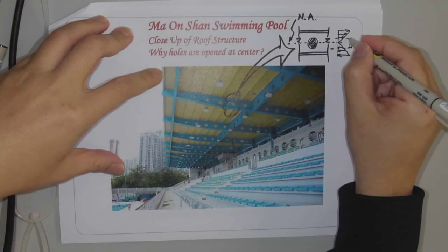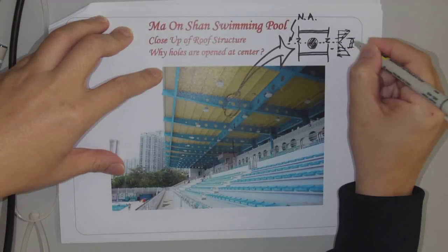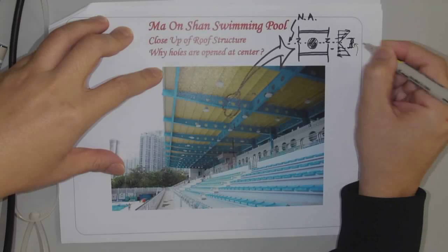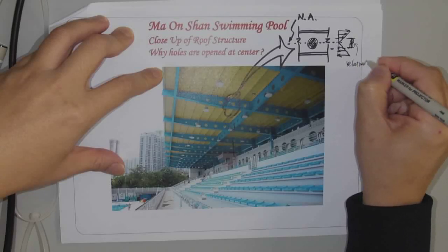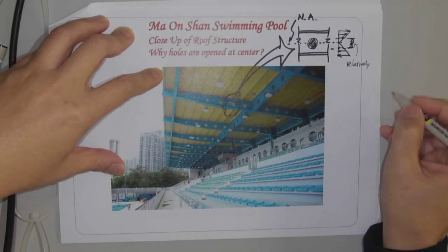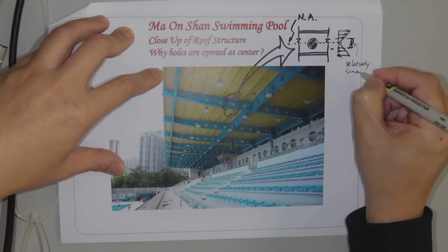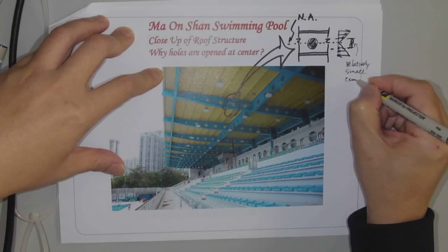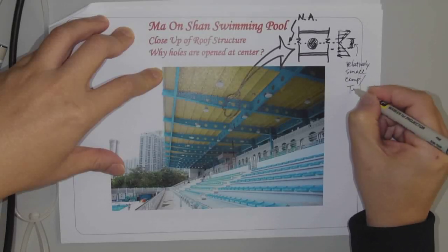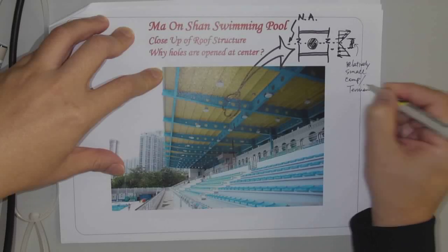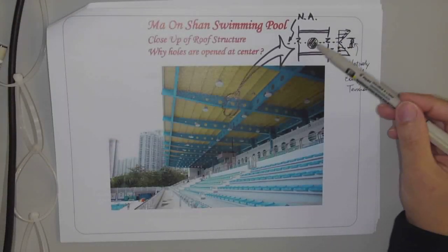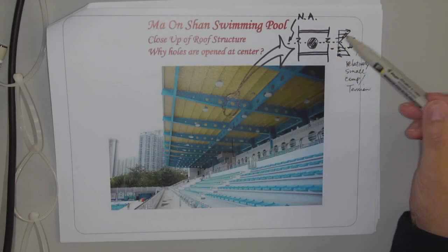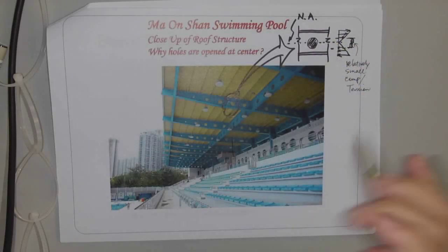So this part of your beam is subject to relatively small compression or tension. And that's why you make your opening around that region, not near the top, not near the bottom.